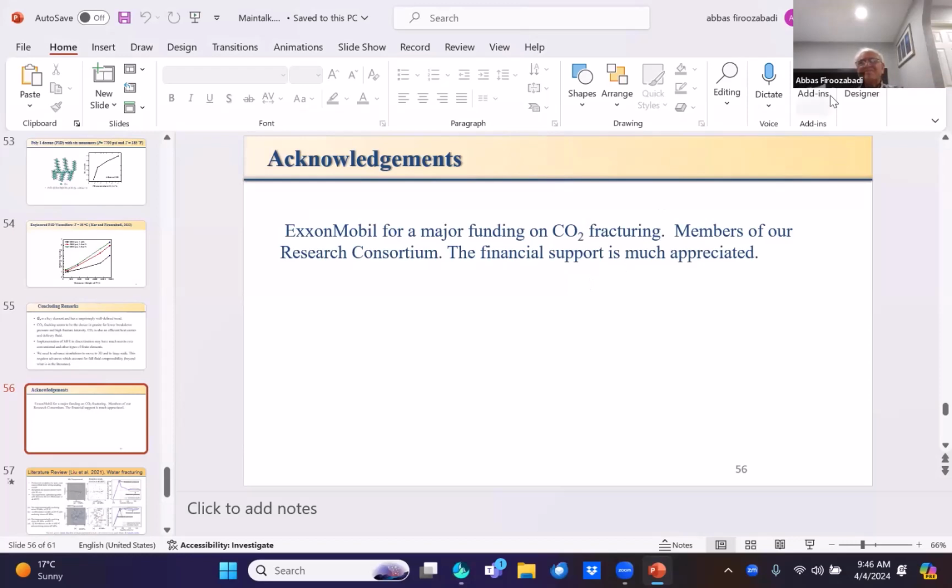Professor Bazant is wondering if the phase field model, he's suggesting, uses linear elastic fracture mechanics, and by virtue of that, it misses the enormous effect of crack-parallel stress on the fracture energy. I guess he's seen this in some gap tests that he has done. I think there are different issues that have been brought up, or are already in the literature, and it seems that for some of these issues, there is, or has been, a way around.